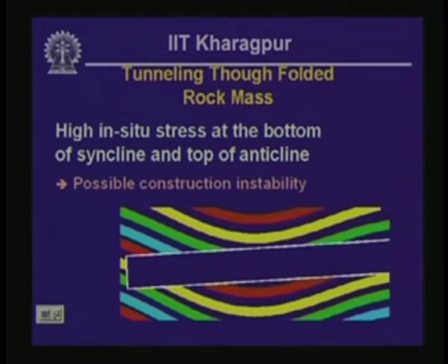syncline fold. Here, as we have discussed, the vertical stress near the bottom of the fold is going to be the largest, and that is true for each one of the layers that we are seeing on this slide. So, these localized increased values of stresses will have to be considered when the tunnel alignment is decided and the stability issues of the tunnel wall are addressed.